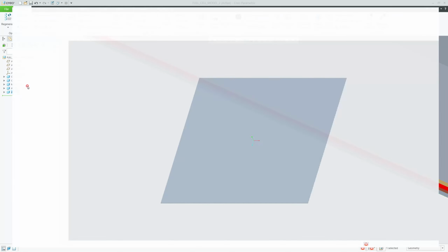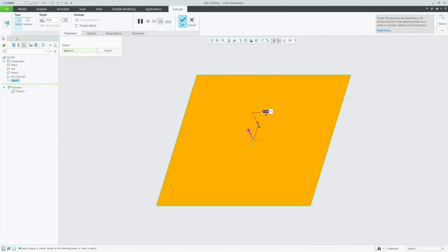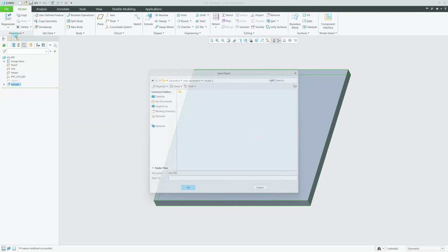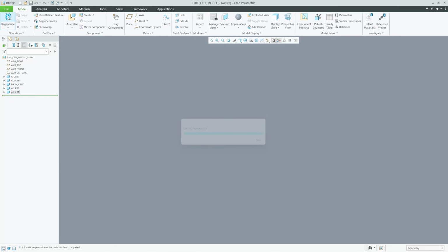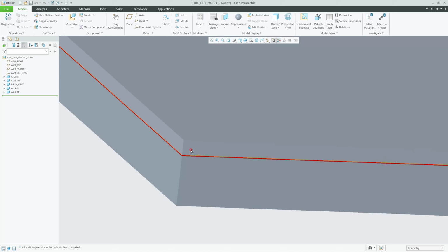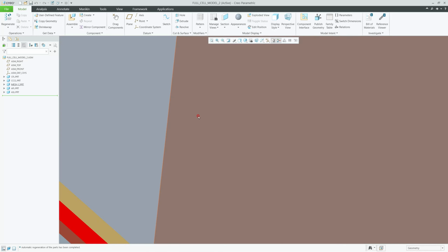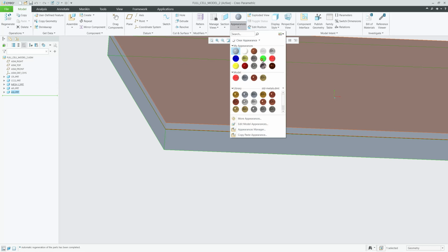So we'll open it first and then extrude the mesh, edit the mesh, and that's 1 mm. So this will be 1000 micron thick. And now regenerate. We made some changes in the geometry, so it's better to regenerate it. And now we can see in the geometry that the anode support layer is really thick compared to all the others except for the mesh, so it's very thick. And for the anode support layer we can change it to, for example, green.